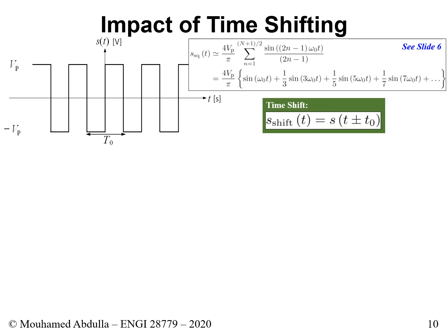Now we ask ourselves about time shift. Time shift, like I told you, is related to shifting the signal horizontally. If you do s of t minus t naught, it means that you are shifting the signal to the right. So when you have minus t naught, you're shifting the signal to the right by t naught, whatever it is, 5 seconds, 5 milliseconds, 10, 12, 1.3 milliseconds, 1.3 seconds, whatever it is. We don't know what it is. It's just a generic identifier here. But anytime you see a minus, it means the signal is shifted to the right.